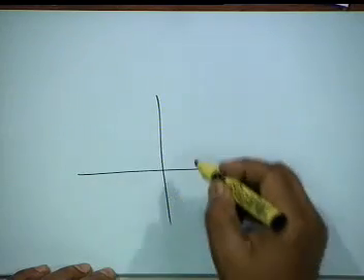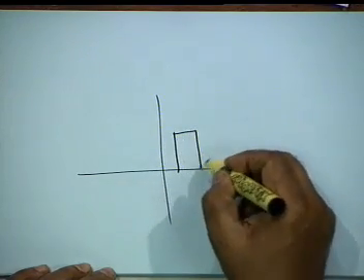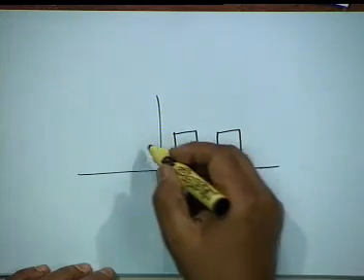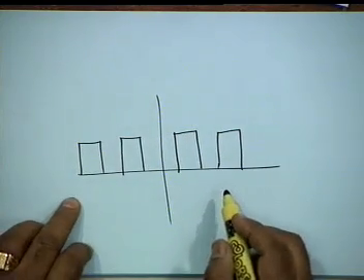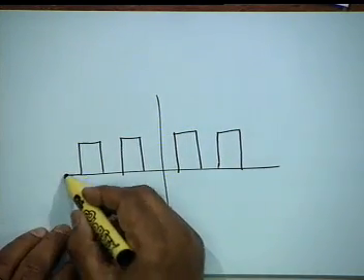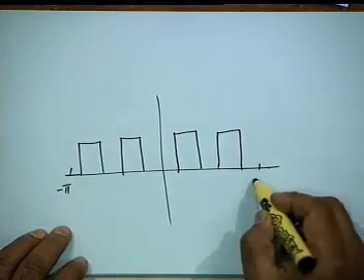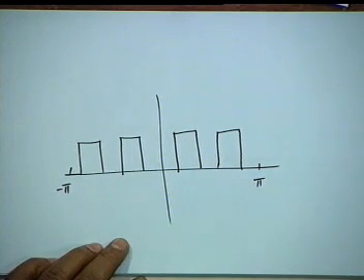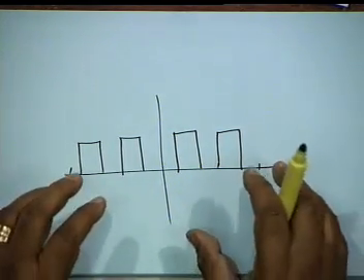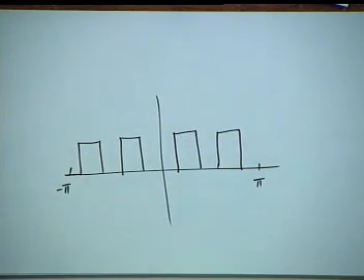You can have multiple pass bands. For example, let us say you have something like this and so on. No question of transformation, you just integrate. You have minus pi here and plus pi here, so you shall have 4 parts of the integral, okay, and design and obtain the corresponding formula and go ahead.